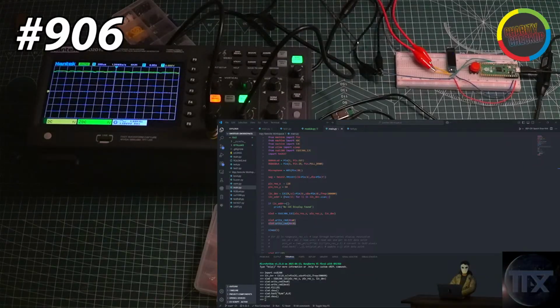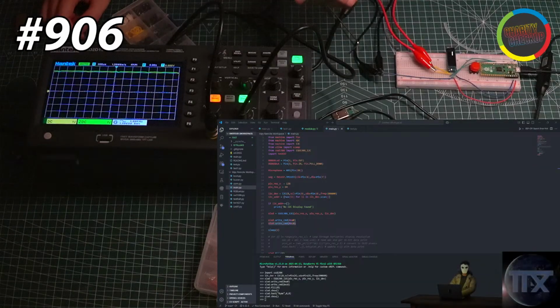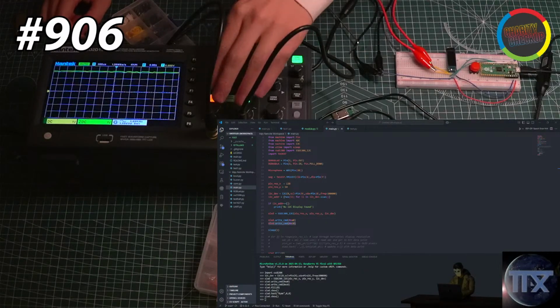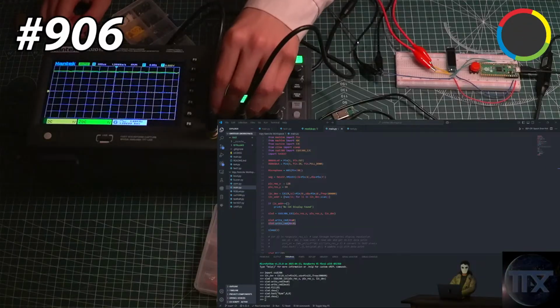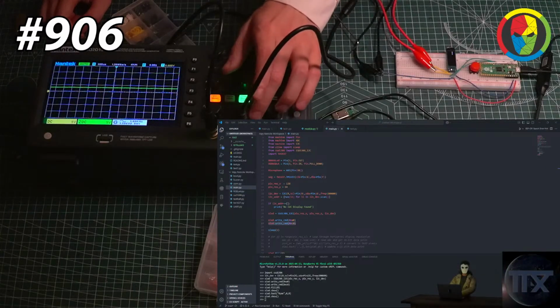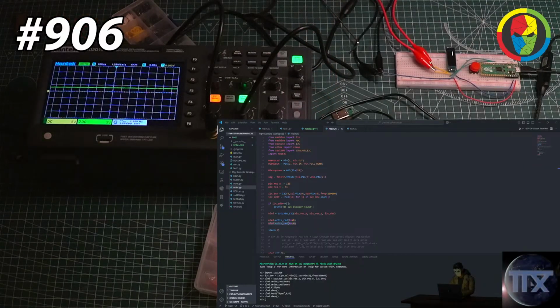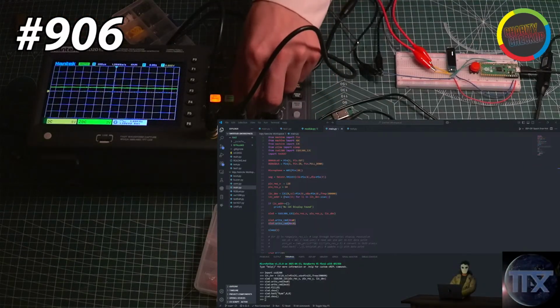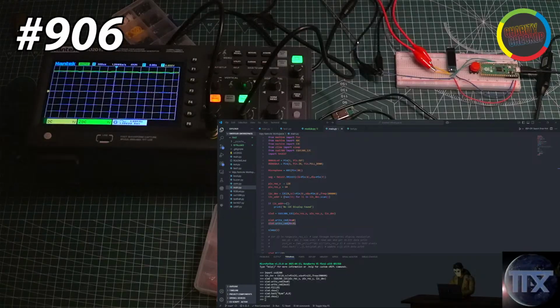Oh, there we go. I should have done it at the very beginning. This is much better, isn't it? Because now on the stream you can see the contrast. Okay, so yours is at the top, actually. You have a different operating system, which is fine, but those big knobs still just adjust the voltage levels for each channel. And I do want to keep it at 5 volts so far. I would keep it at like 1 volt because you can see the 3 squares. So 3 volts is 3 squares high.